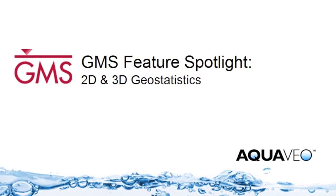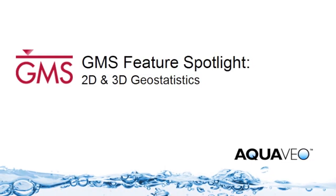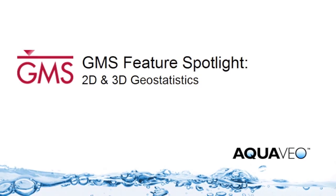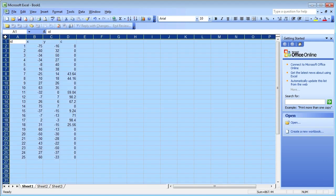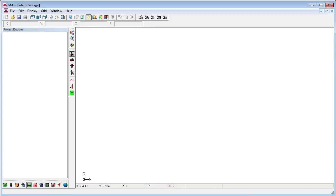GMS supports 2D and 3D geostatistics, or interpolation. Interpolation is done from discrete points called scatter points. Scatter points can be created in GMS, or imported, or created from other objects. I will import some scatter points by copying from an Excel spreadsheet and pasting into GMS using Ctrl-V.